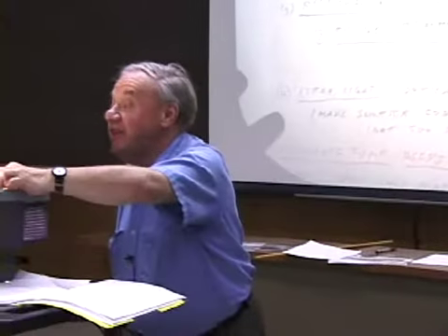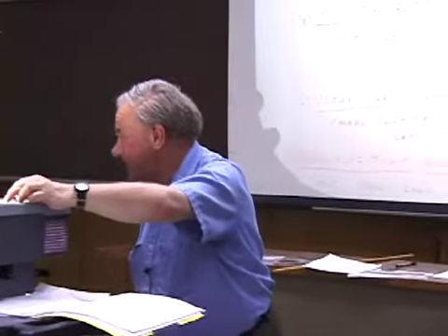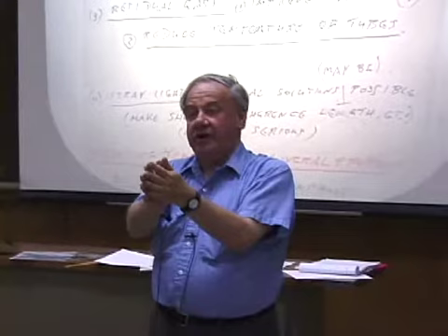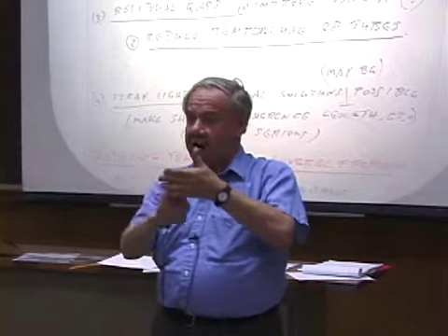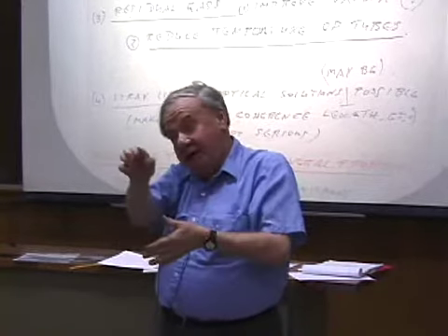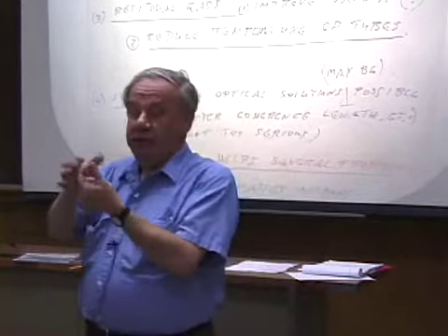You can push that further and further, and as it happens, the very first laser interferometer I built, which was a long time ago now, 1977 I think, or 1978 in Scotland, was a very weird one. It had quarter-ton test masses, only a few inches apart, with an optical system to measure the distance between them. But that, as it happened, had what still seems to be the very best kind of suspension. It was made on a big scale because we were hanging quarter-ton test masses, but there were actually blades of very high Q aluminum alloy that were 1 inch wide and only a few thousandths of an inch thick. And that's a very good idea.